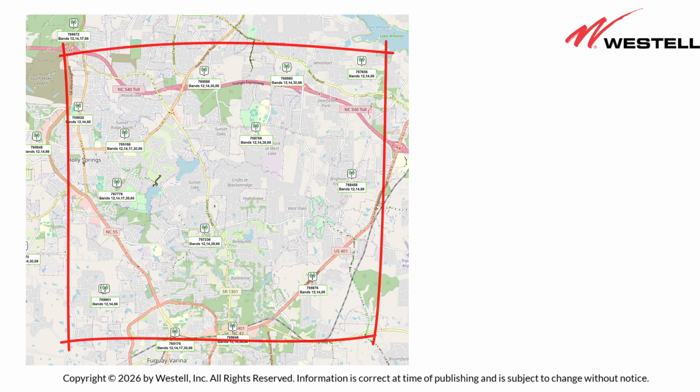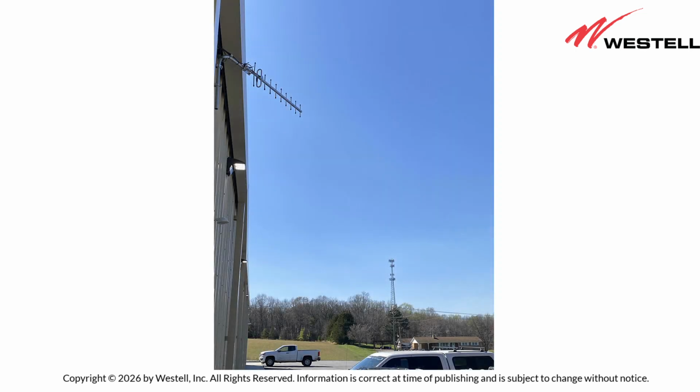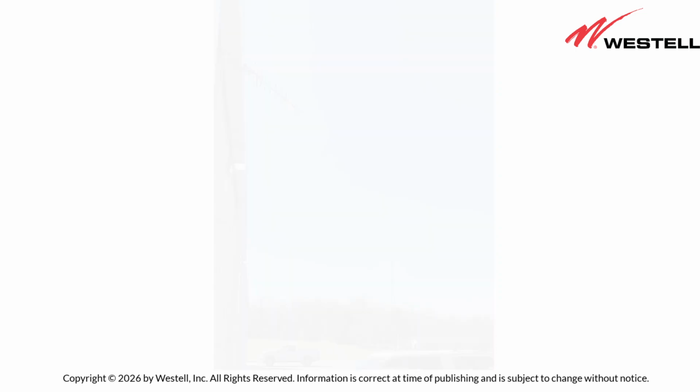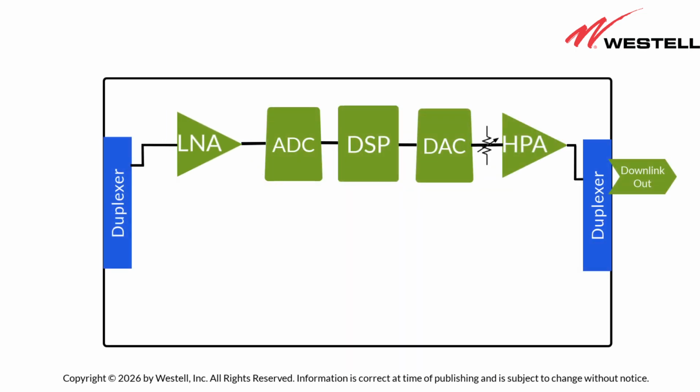What happens to a BDA if it is too close to a wideband transmission? In this block diagram, the LNA and the analog-to-digital converter are prone to overload if a too strong signal is applied to their inputs. When overloaded, their outputs can be greatly distorted. Therefore, the lesser of two evils is to attenuate the strong signal to prevent the overloading.